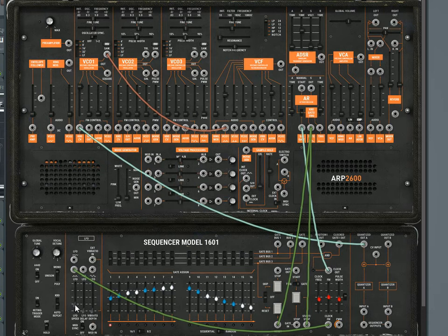We'll reduce the frequency of the low frequency oscillator, and now the effect should be obvious. So this is the low part of the LFO, high LFO, low LFO, goes high again. We could also use one of the envelopes to modulate the speed of the clock, or any other control signal. Let's disconnect that cable, and we'll go back to the gate buses and focus there for a while again.